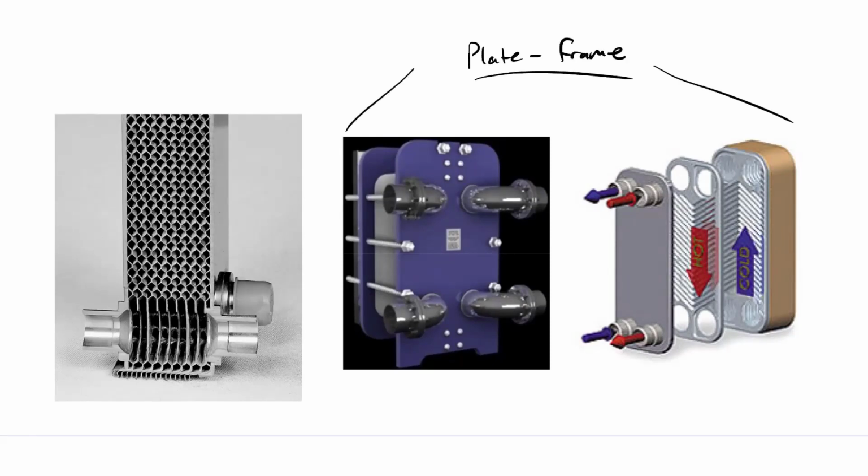So these two over here. Plate frame is a type of heat exchanger where you have a bunch of plates, right? Maybe there are these etched plates or there are little microchannels carved into them. And you just stack them up inside this frame. It's a little hard to see, the resolution didn't hold very well, but you have hot fluid coming in this port here. And if you can maybe squint, you see that there's a groove cut in this part of the channel that allows the flow to move through this hot plate all the way down to be collected at the outlet.